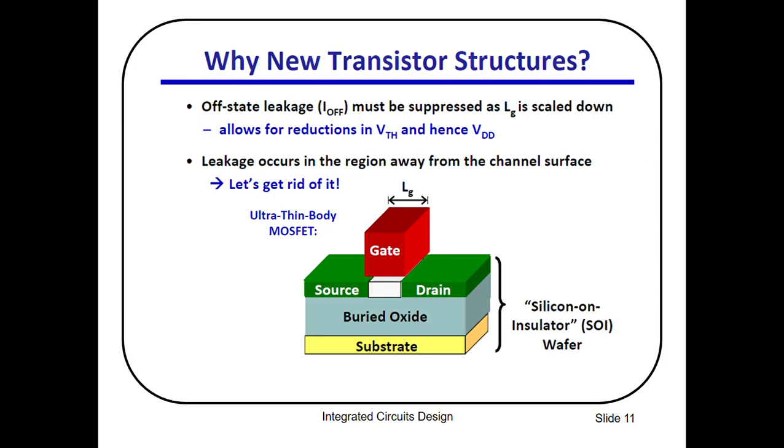So why do we need the new transistor structure? Basically, the main advantage of multi-gate devices is improved short channel effect. Since the channel is controlled electrostatically by the gate from multiple sides, the channel is better controlled by the gate than in the conventional transistor structures. Unwanted leakage components are reduced and small transistors can be used to continue the cost reduction through miniaturization.